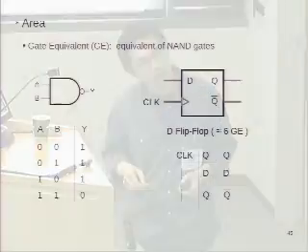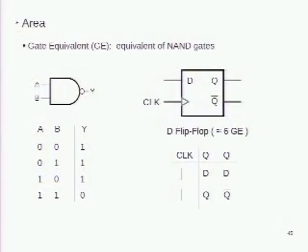And also with this gate, actually, you can construct any functions. So this is the memory cell in hardware, so you use it to store information. Roughly, the area of this thing is 6 gates. So the size of this thing is 6 times this, roughly. It depends on the library.